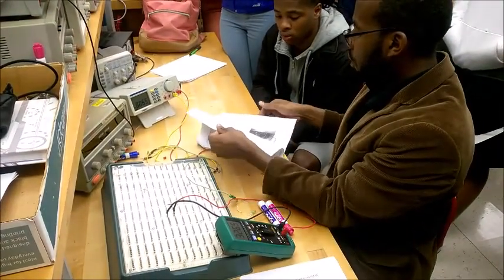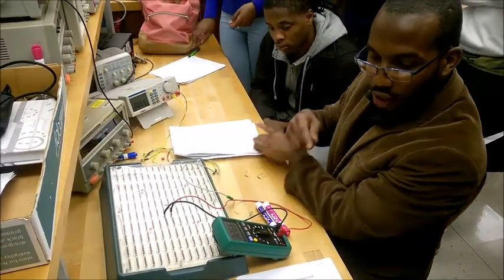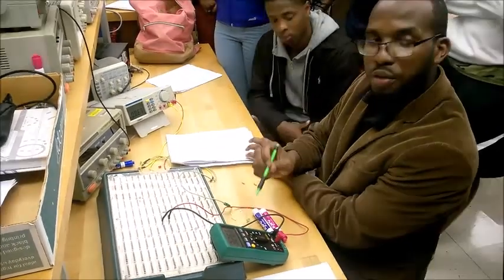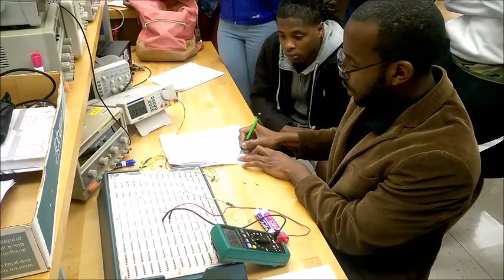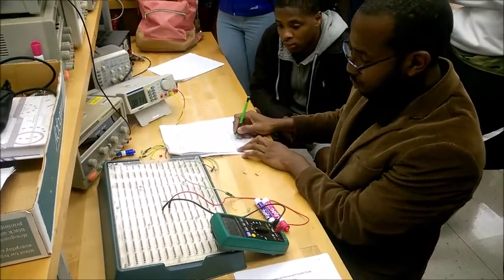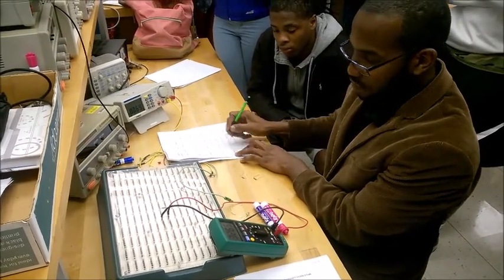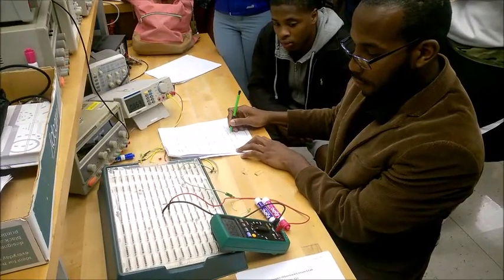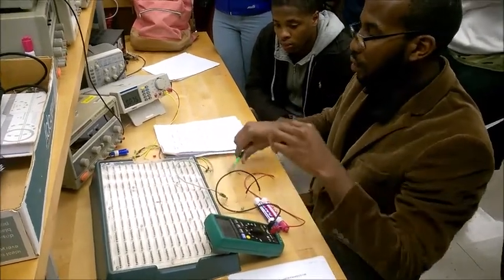Now, if you notice in your lab, we have a data section here. We have resistance of the resistor. Now, we don't have a 470 ohm resistor. This is showing 326.6. It's actually a 330. Now, there's a way you can find the resistance of the resistor by looking at the colors. We'll talk about that later. So I'm going to start here, 326.5. I'm going to take another measurement. 326.5. I'm going to take a third one. 326.6.